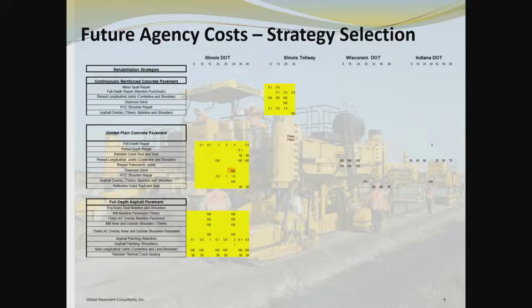Rather than do that thin asphalt, and you'll see the effect of it, diamond grinding, according to the new techniques and the new configuration of grinding pattern, will achieve the same result without having to overlay it, without changing grade, without doing all the other things that we really don't want to do on our mainline roadways.